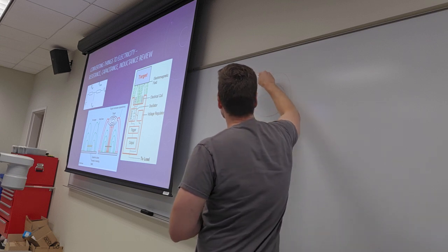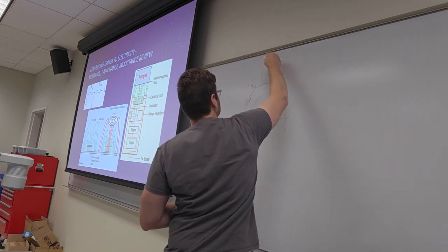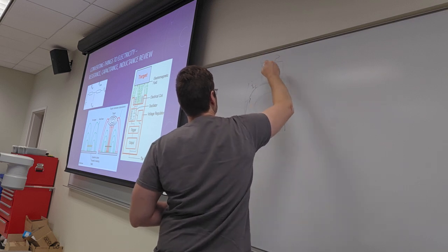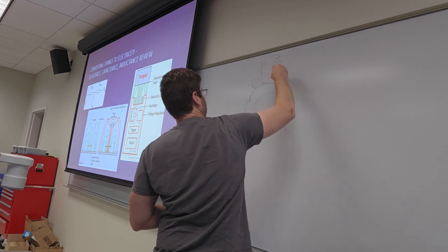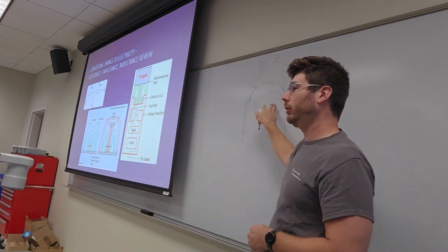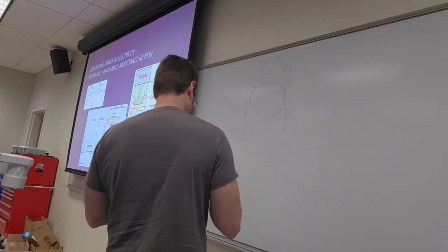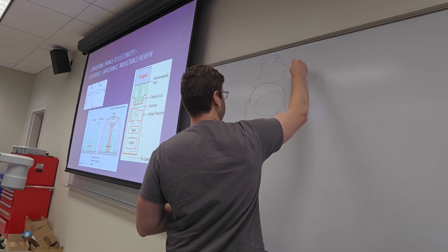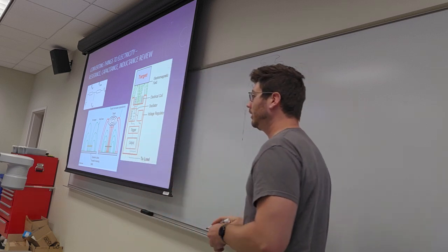There's an inductance in this coil. When you park a big block of metal over it, like a big motor or a motorcycle, the magnetic field couples between those two pieces of metal, the coil being one piece of metal and the motor or whatever being another. Then the system can sense this disturbance. The amount of mutual inductance, it's called, changes.